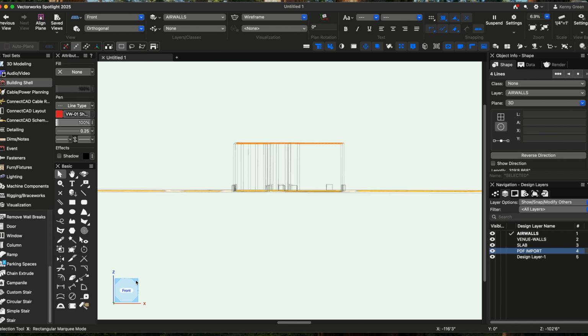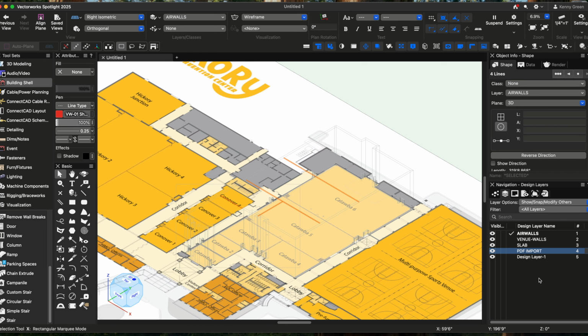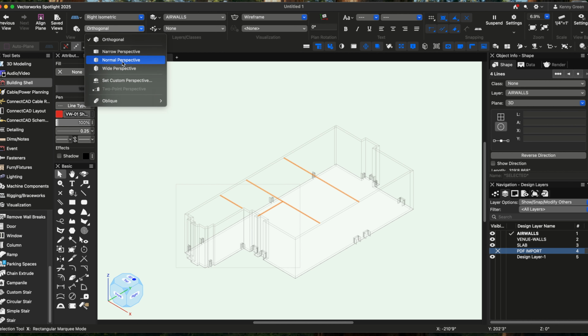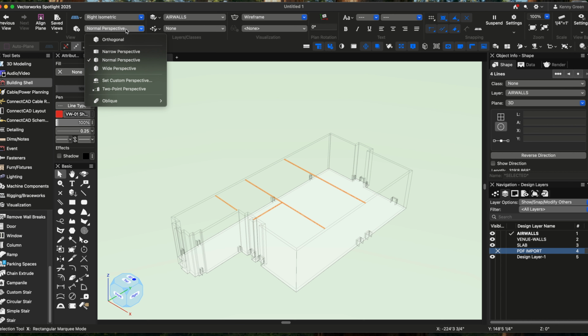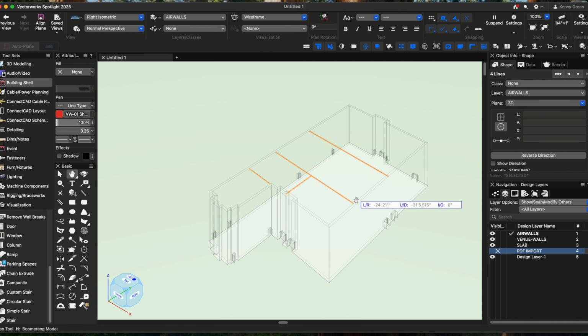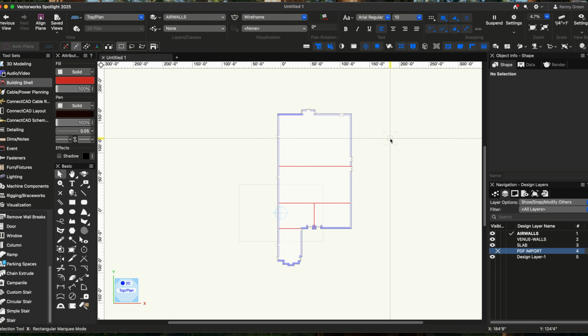So now if we go into a right ISO, you can see that those air wall tracks are now at proper trim. Turn the PDF off. There we go. Let's put this more of a normal perspective. Looks a little skewed. There we go. And as always, put it in 2-point perspective, which makes your vertical walls appear vertical. Much more realistic. And that's probably going to take care of what we need to do right now.